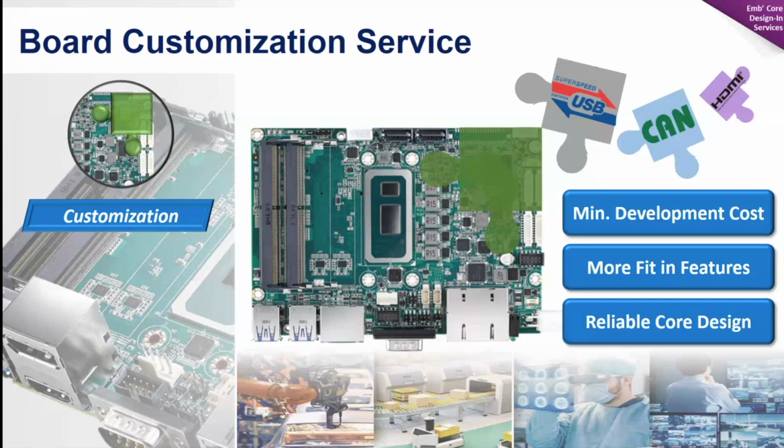But doing that COM Express approach can take a long time because that CPU module does not have any I/O. Basically you pull out the signals to an interface board, maybe a carrier board, and the interface can be a high-res connector, other things, or maybe gold finger. So this means a long design cycle. We do have customers who say, hey, my customer expects this to be delivered in a few months or maybe within 1 year. I have a short testing time. I need to customize certain things fast. Then this becomes another consideration.